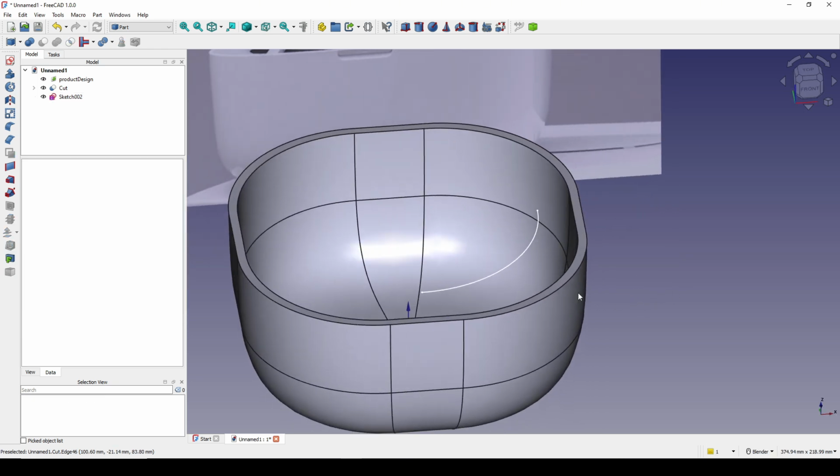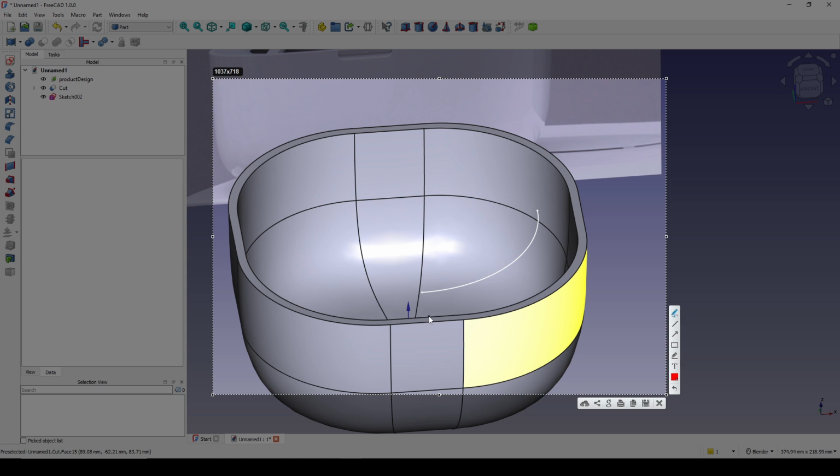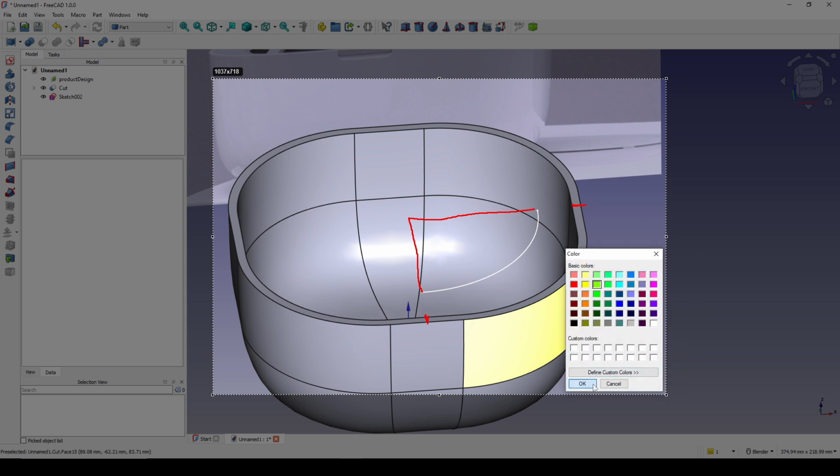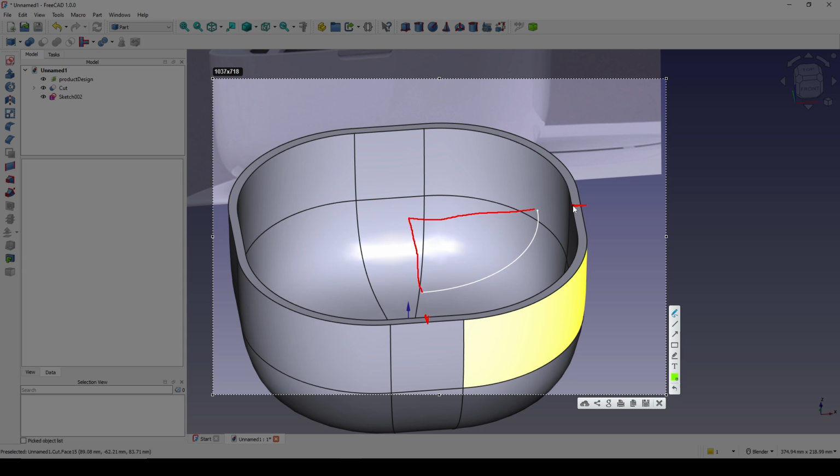The next step is I want to split this surface in half so that I will have a line in here. Split this one so that I have another line in here, and also create one line like this and another line like this, so that later I can create a plane curve to blend in between, so that this point contact will have the G1 continuity, and this one will have G0. This one will have G0 because I don't want any continuity in here, and also the same in here. And from there, after I have these two plane curves, I will fill the surface in between.